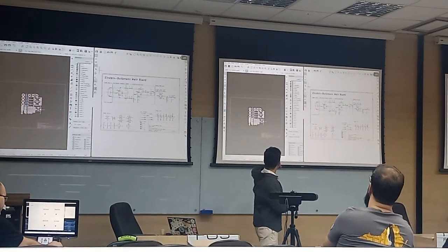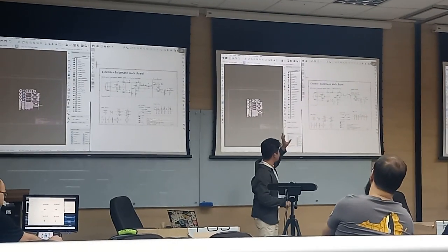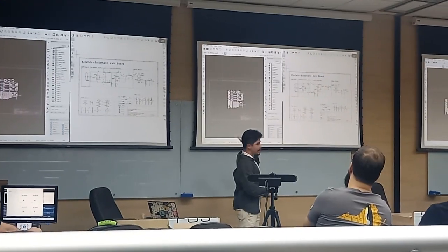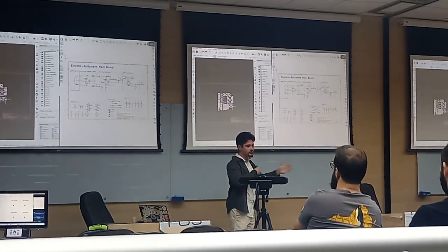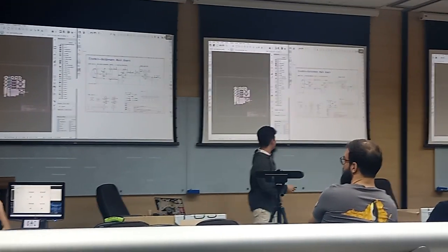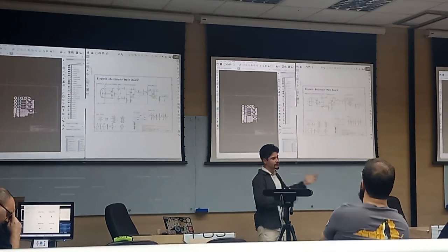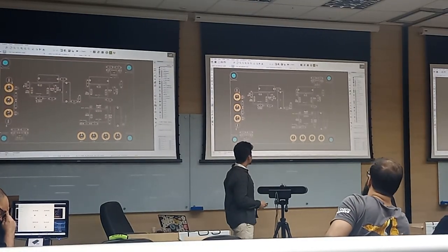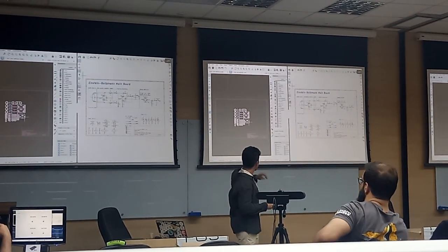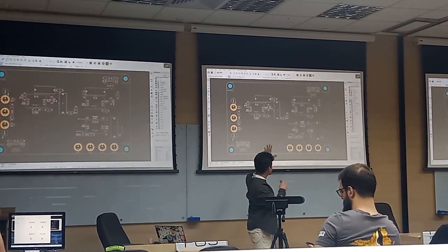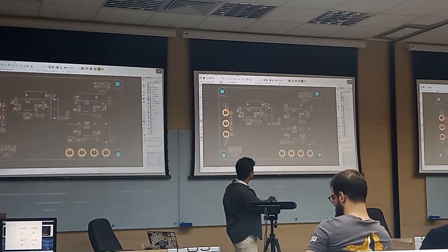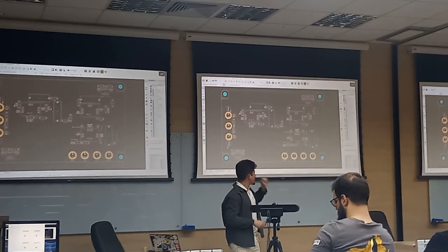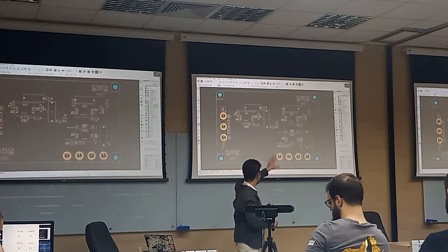And it works when you change, for example, something on the schematic, you can just push it to the layout straightforwardly. It's not only at the start. The two of them are coupled. This is a very interesting thing. So yeah, you put the components on the layout, just place them where you want, define the edge cuts of the board, put some pads, and you actually have a board.